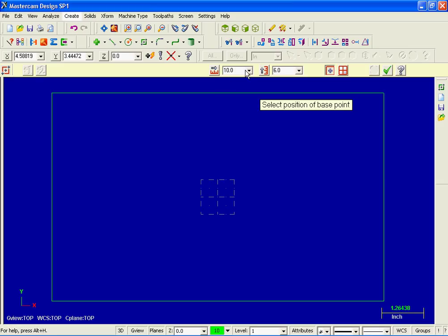Now I'm going to click in the white section for the width. For the width of this rectangle, I'm going to look at my drawing, and for the width there are 3 horizontal dimensions. So I'm going to type in 2.5 plus 3.5 plus 2.5. There are 3 horizontal dimensions at the bottom of the drawing. Now I'm going to hit Tab.